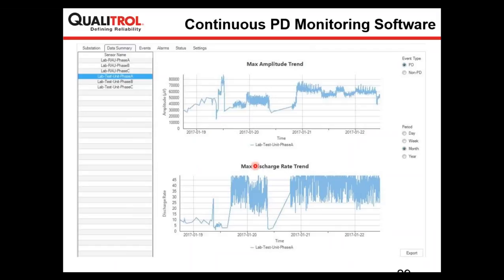And in this way, by seeing the trend of partial discharges, if there is a constant trend which is not increasing, then that's safe. And if you see a gradual increase in the trend, then it means this partial discharge activity has become activated and it will lead to the failure of cable insulation.